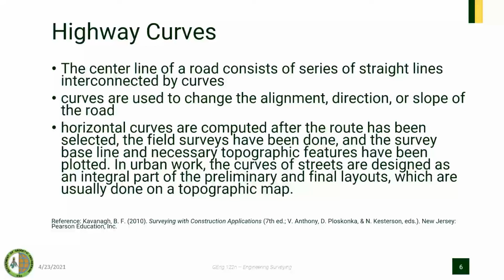Again, the center line of our road consists of a series of straight lines interconnected by curves. Curves are also used to change the alignment, direction, or slope of the road. The horizontal curves are computed after the route has been selected, after the field surveys have been conducted and the necessary topographic features have been plotted.